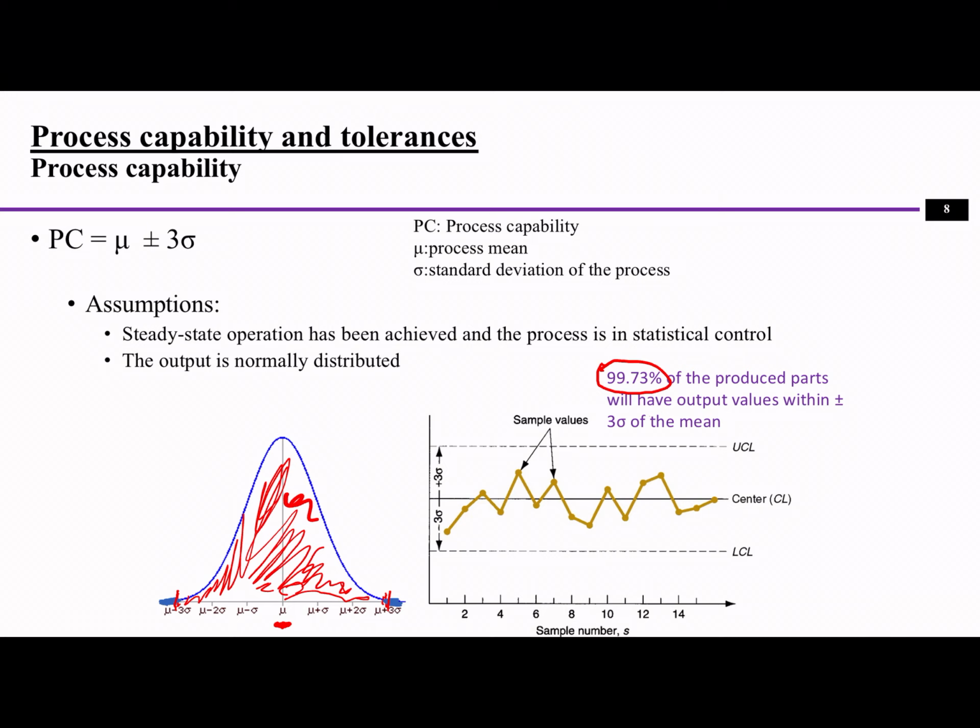So this is a 3 sigma control. When we are looking at SPC, we also need to know the chart. The chart is composed of axes of the sample numbers 1, 2, 3, 4, until whatever number of parts or samples you collected, and the dimensions or quality measures.